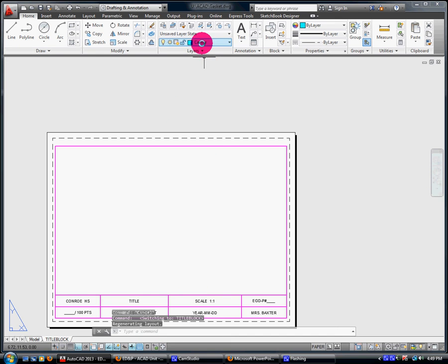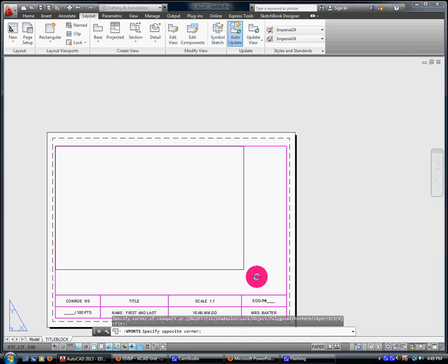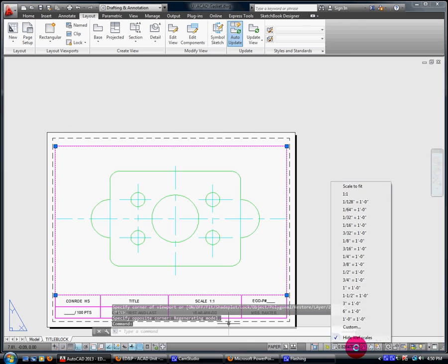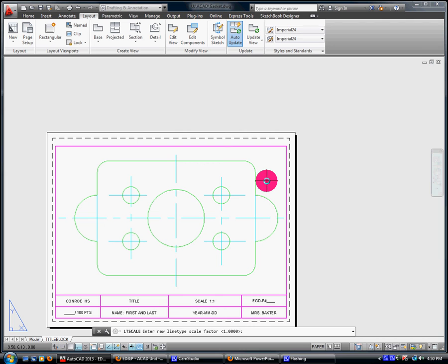Put it over into my title block. Make sure that my scale is set correctly. Remember, if your line type scale obviously looks wrong, remember back to when you drew by hand. Doesn't matter if it's AutoCAD or by hand, there's certain things that it needs to follow. So you can do your line type scale and you may change it around to look at things. So you may need to switch the line type scale so that the line types look correct. If you look at it visually and it does not look right, something's telling you something's off, right? Use this to help you. And then it's just a matter of going back,